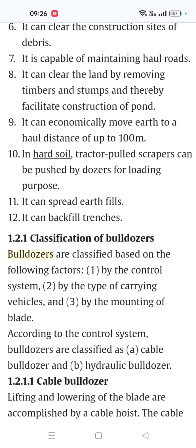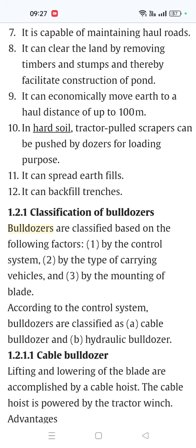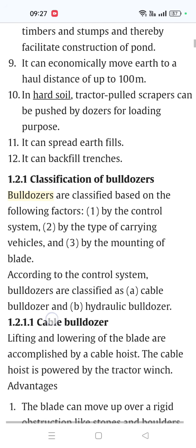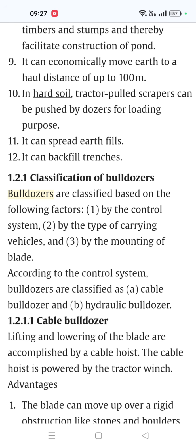9. It can economically move earth to a whole distance of up to 100 m. 10. In hard soil, tractor pull scraper can be pushed by dozer for loading purpose. 11. It can split a field. 12. It can backfill trench.